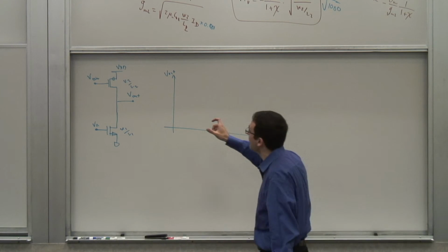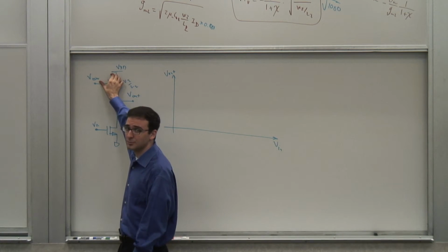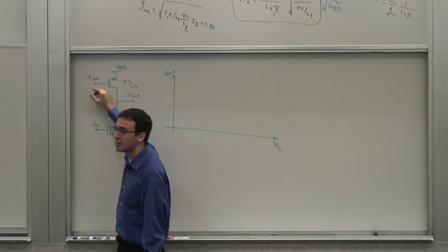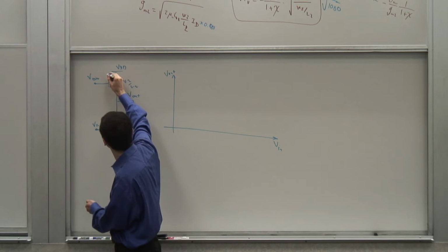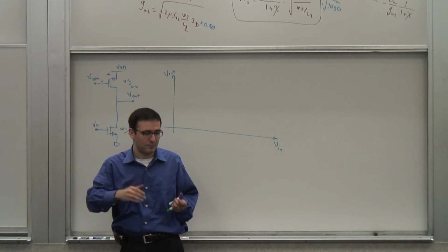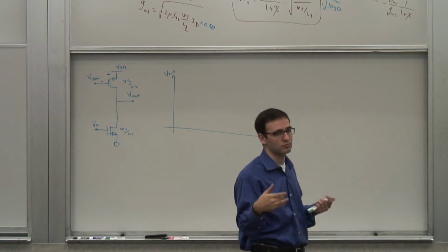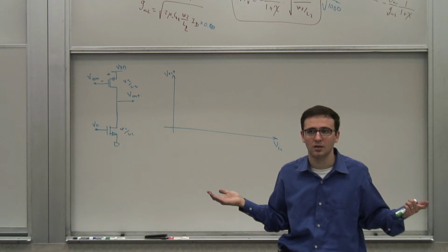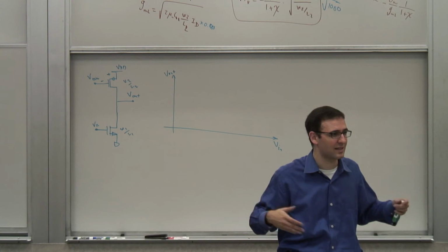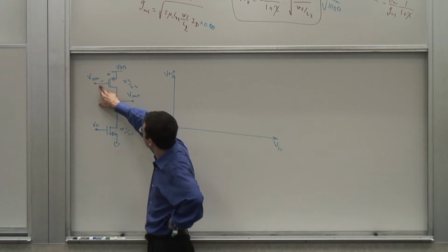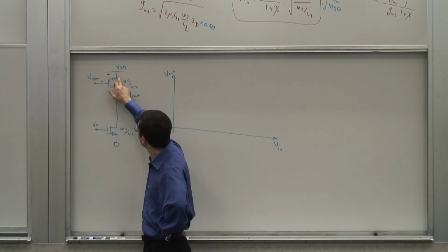I've maintained a V-bias, which obviously has to be below the threshold here, because it has to be lower than that. But this voltage is positive enough, so I have passed the threshold, so the transistor needs to remain on, because that's a constant voltage, otherwise it will be off at all times. And there will be no current flowing within the stage for any V in. So I basically have bias to set something, right?